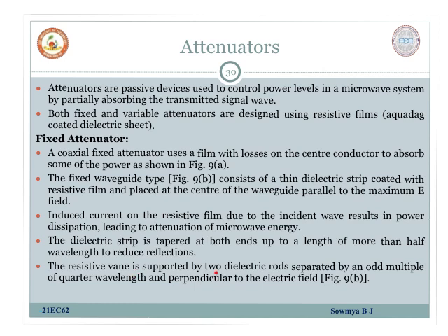And the resistive vane is supported by two dielectric rods separated by an odd multiple of quarter wavelength, which is perpendicular to the electric field.